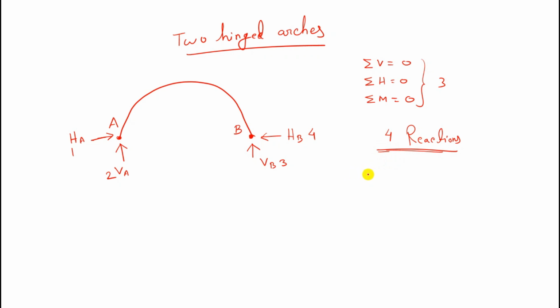That's why it is an indeterminate structure, and the degree of indeterminacy will be 4 minus 3, which is 1.